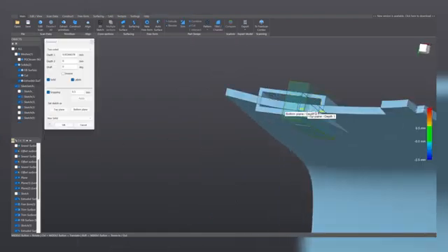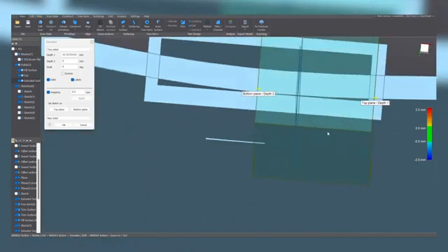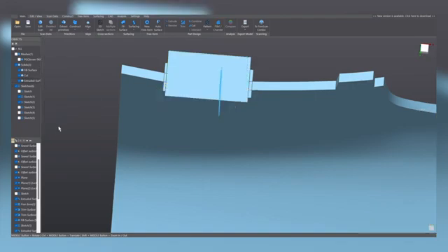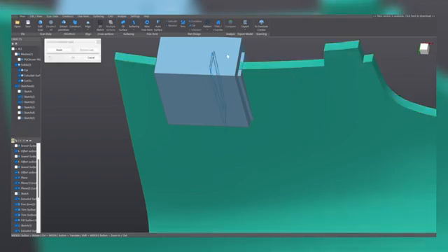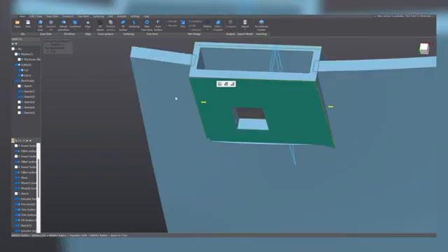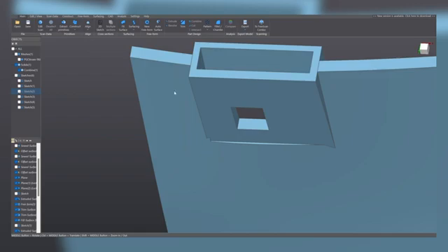Select the rectangle, and let's extrude it until it goes inside the walls of the new solid that we have designed. And likewise here. New solid is again selected. Click on OK. And now we choose this solid, and we tell the software that we want to cut this solid with this one. There we go. Now we are good to select both solids with the Control key and combine them together. Let's hide these sketches.